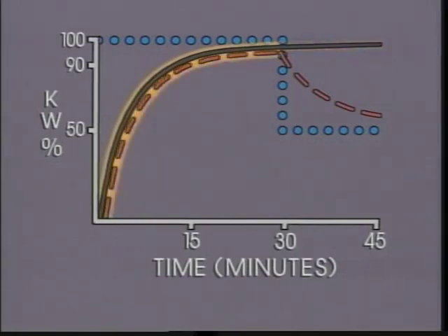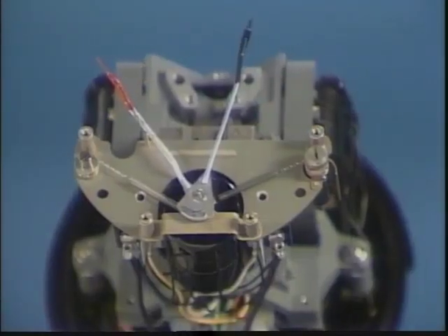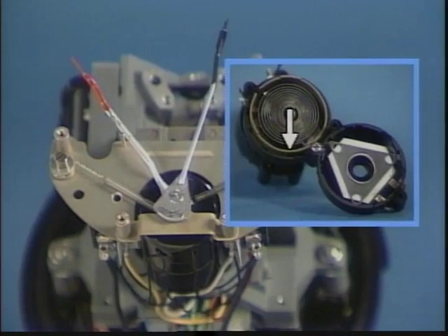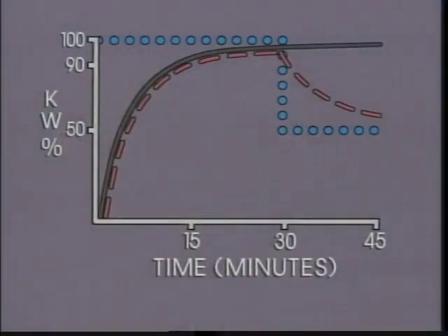The curve of the pusher arm and pointer is a typical representation of the temperature changes that occur when a substance is exposed to a steady heat source. In a thermal demand register, the heat source is the heater elements, and the substances being heated are the bimetal coils. The coils respond to the heat by moving the pusher arm upscale. The reason for referring to a thermal demand response as a lagged method can be explained using the curve that represents the motion of the pusher arm and pointer.